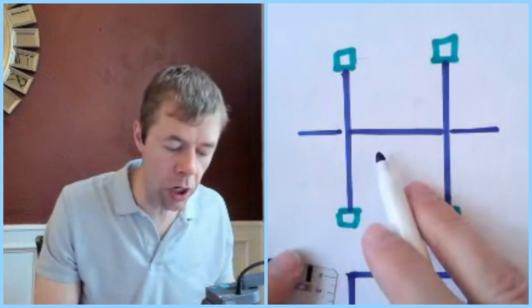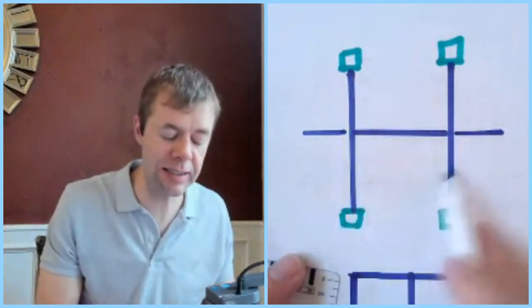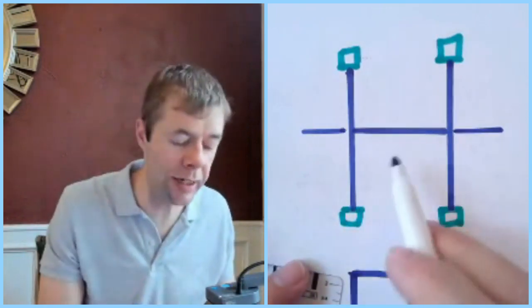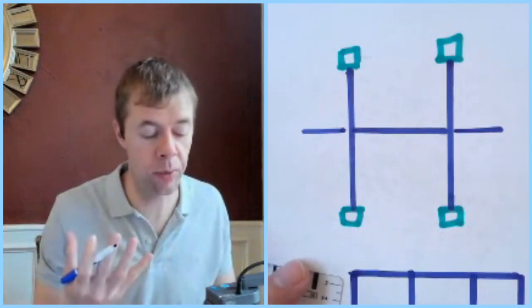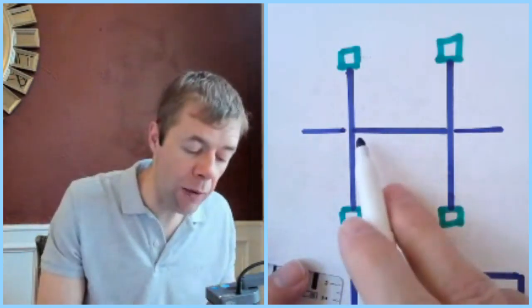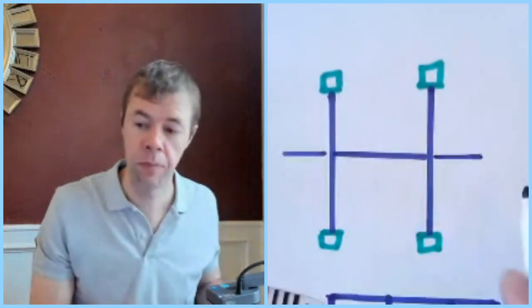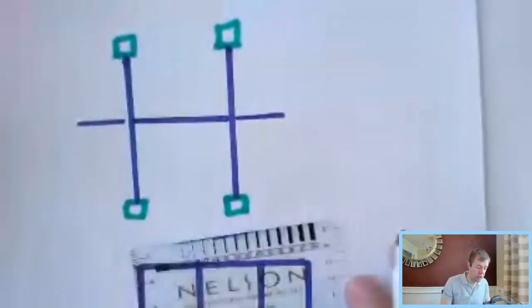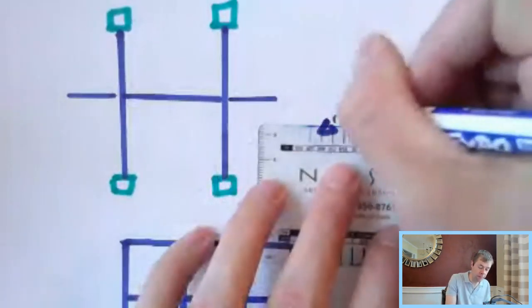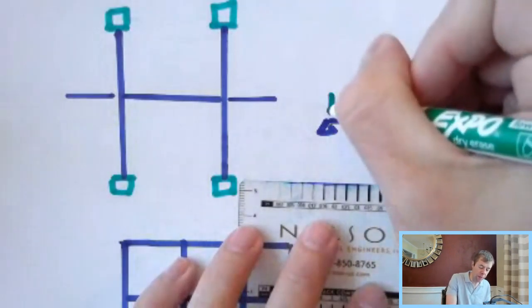Now, if I think about my loads, one way to design this system, not the only way, but one way, and this is what I would recommend if you're working on a project for my class, is I would recommend treating this beam in the middle as a simply supported beam. So let's zoom me out here. If I design this one as a simply supported beam in the middle, so beam, beam, and it's got its load on top of it.